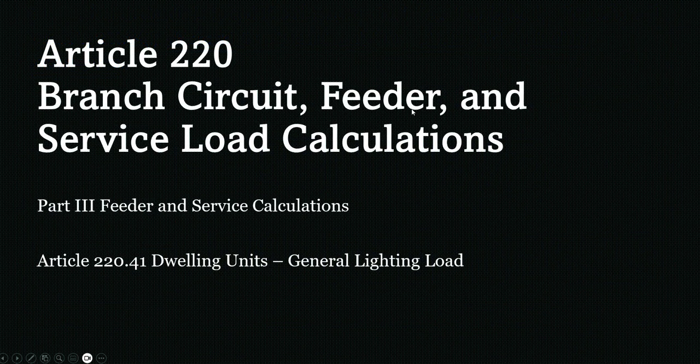And quite frankly, that's what I was told when I was calculating how many lights to put on a circuit. 10 things. Don't count switches because there's no load there. 10 lights. Well, today, if you do the calculation and go based on that, you would really be leaving a lot of room on the circuit. Now you should be able to get more than that because of the decreased lighting load in really any application, whether residential or commercial.